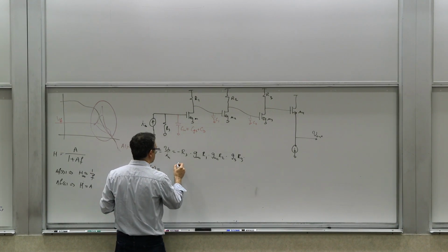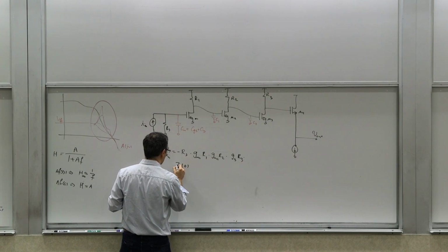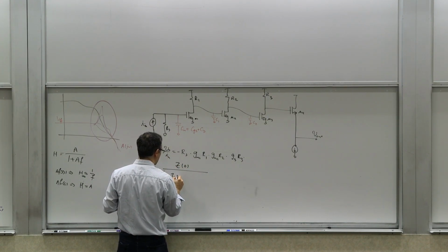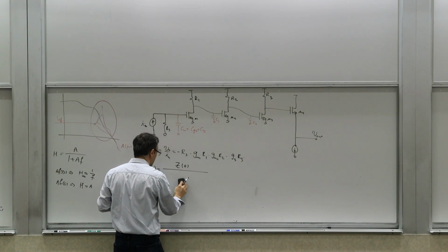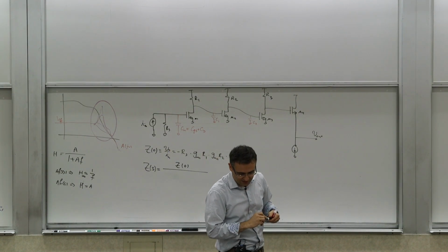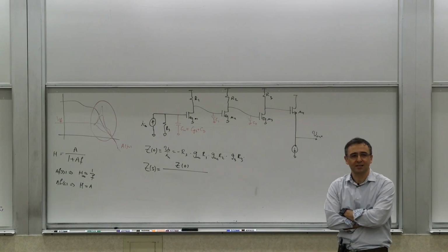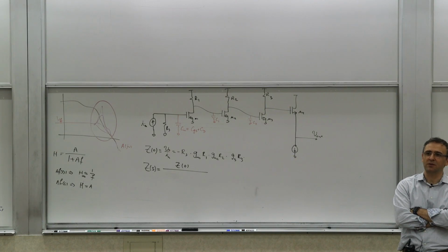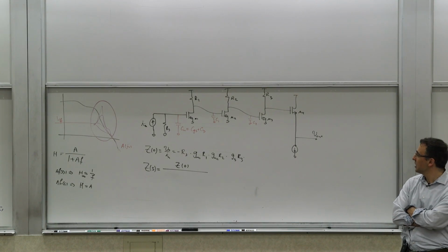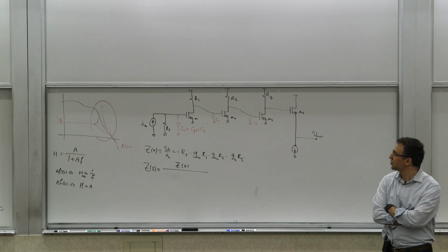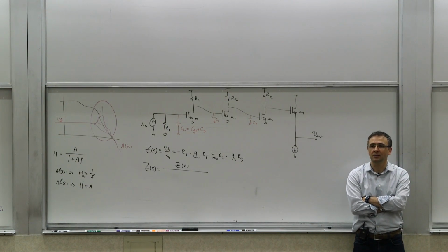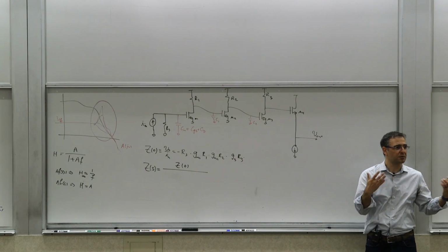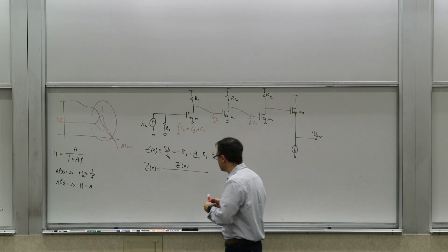So we know that the transfer function looks like Z of 0 over 3 time constants, 1 plus tau in S. We haven't discussed this yet, but we know one more thing. These time constants are also uncoupled, right? Because the resistance each one of these capacitors sees is independent of whether or not the other capacitors are shorted or opened. Shorting or opening the other capacitors would not change the resistance seen by each one of them. So there are 3 uncoupled time constants. There are 3 real poles.